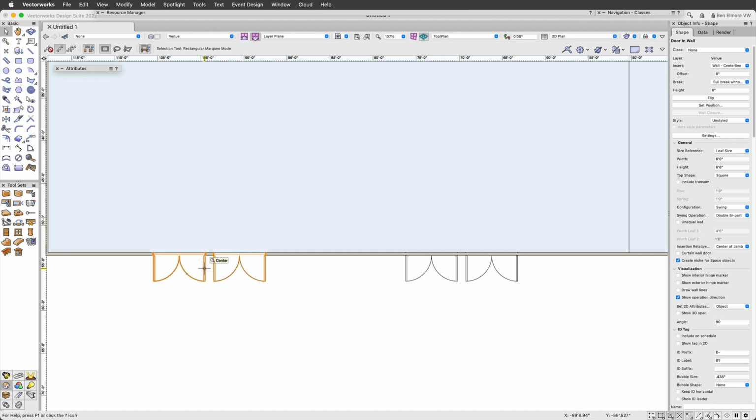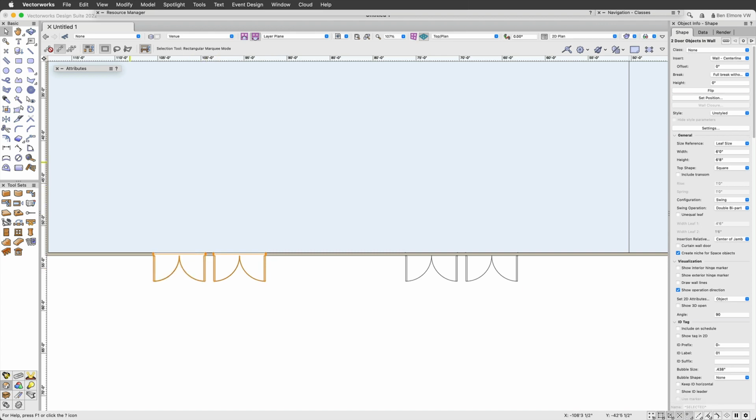And there's a copy. So if I select both of these, let's use this Move by Points tool. The second mode, which is Move and Duplicate. I'm going to leave our object retention mode on and say duplicates 1. Now we can just go point to point.